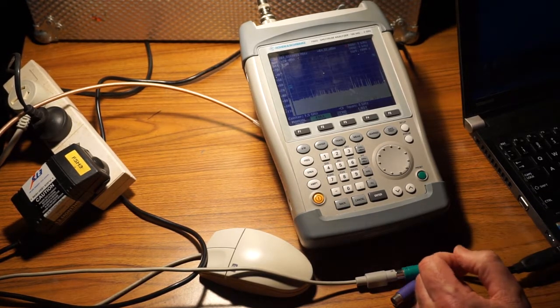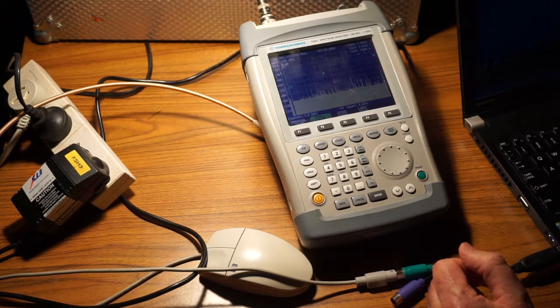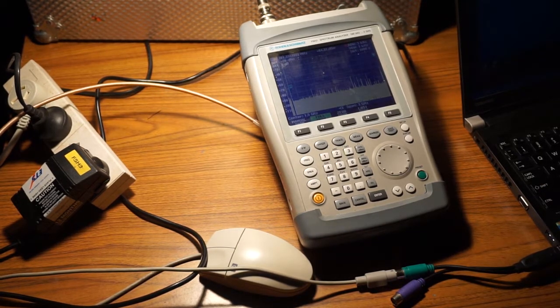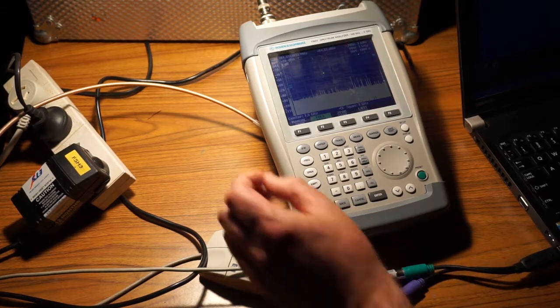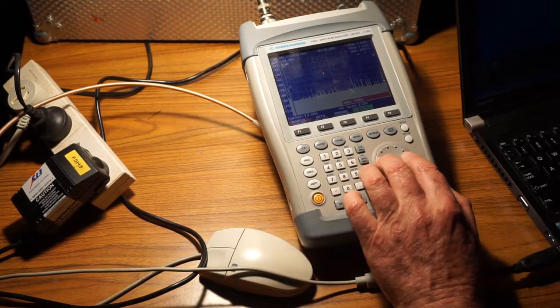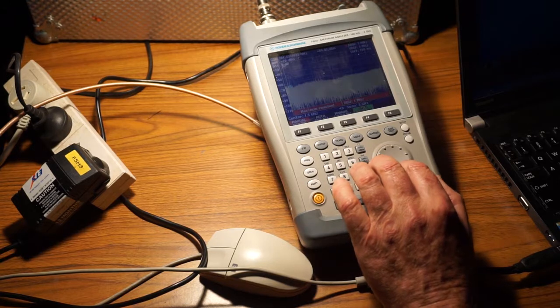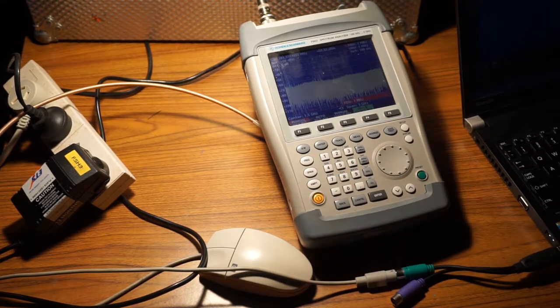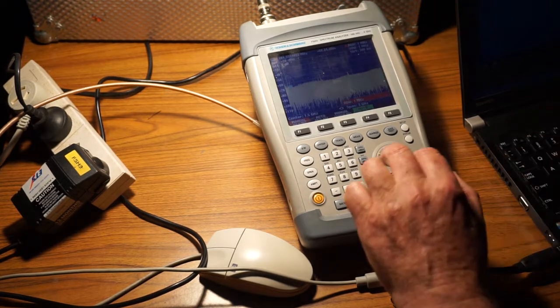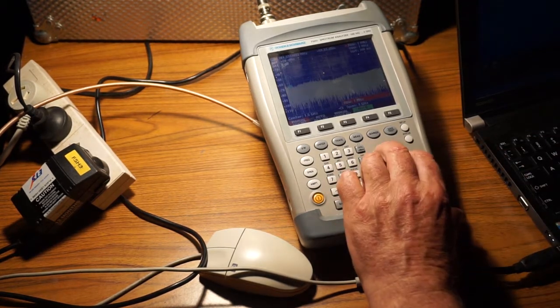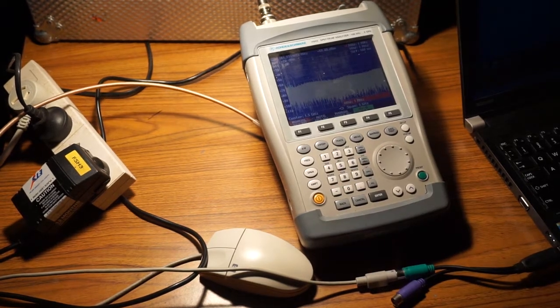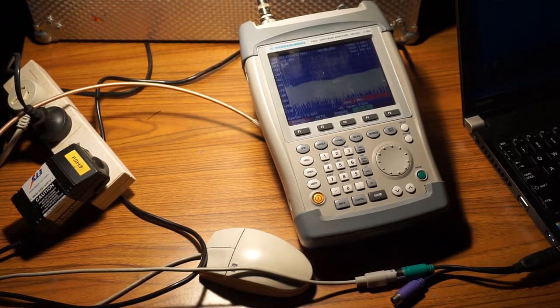And that's less than 0.1 of a watt. We can see how slowly that's spanning, again because of resolution bandwidth. So let's speed that up to 1 meg, and there we go. And we see how the noise jumped up. We talked about this when you change the resolution bandwidth. So I'll just do it again. I'll decrease the resolution bandwidth. This is saying 100 milliseconds, so it's sweeping in 100 milliseconds, and this is 1 megahertz resolution bandwidth. This is 100 kilohertz to 3 gigs it's sweeping at the moment.